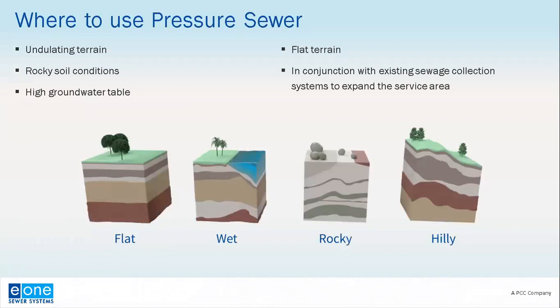So when we're having discussions with potential stakeholders about where to use pressure sewers, these questions typically come up. Where is this system or this technology going to deliver the most value? And the answer is, in most applications. This is no longer an alternative technology. It is a mainstream technology. It's a suitable technology. And the answer is really wherever the terrain is undulating or hilly, wherever rocky soil conditions exist, and where there's high groundwater table.